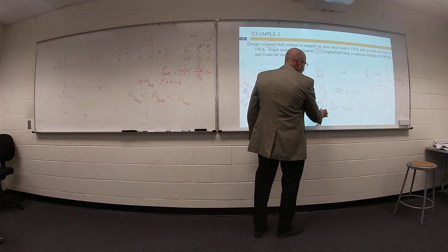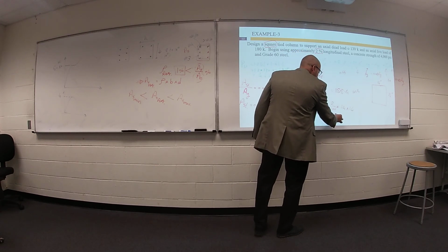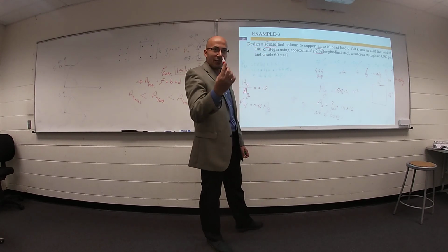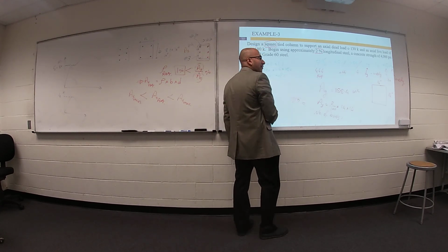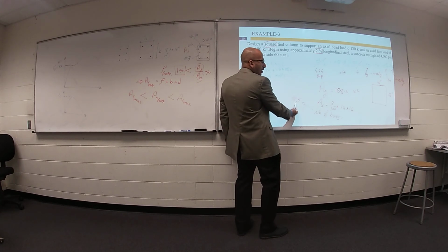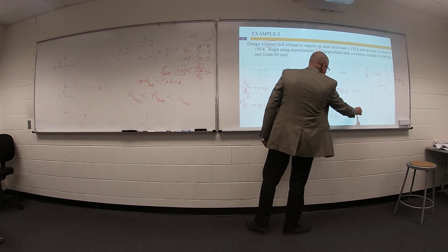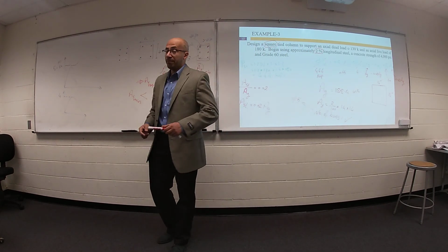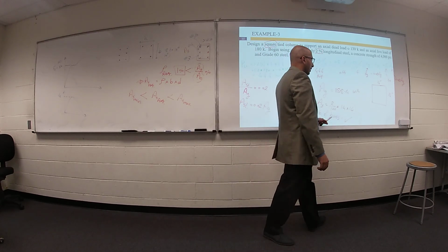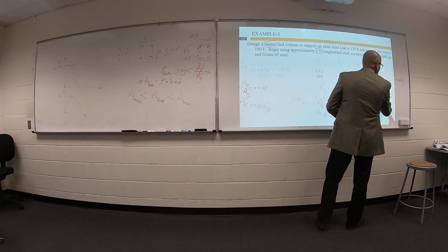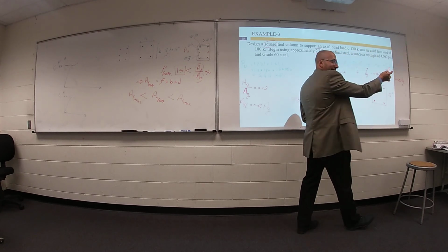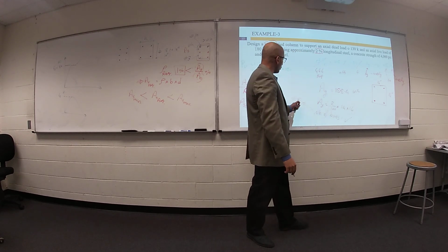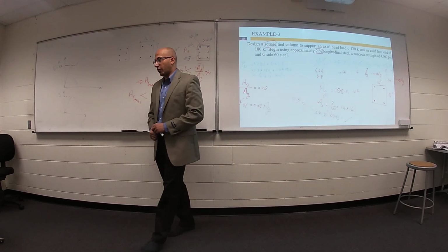Can you tell me the number of bars? First tell me the size of one bar. Which size will you use? Number 3, number 4, number 5, maybe number 5. What is the area of number 5? You can get this area, and with the area of steel, you can figure out the number of bars. Remember, your number of bars must be 4 or more. So if this number is 3, no, make it 4 or use a smaller bar size.